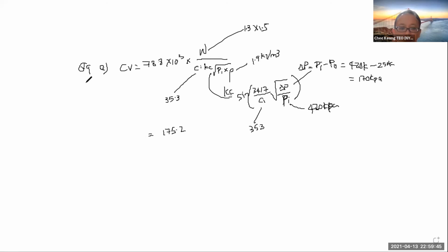Should the control valve be air to open or air to close for the process, and why? Now you are dealing with a control valve that controls boiler steam. Boiler steam means that when it fails, that means no air, right? Fail means no air. Should it close or open? I would say no air means close, because it contains steam. No air means fail, so it's fail to close.